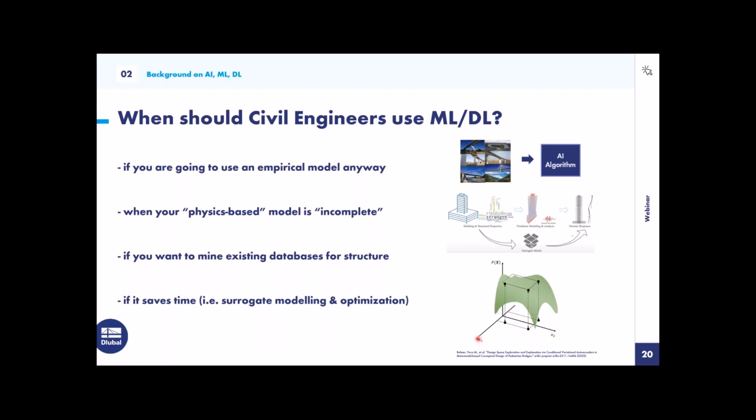Our design problem can be a length, a section profile, or a material. And what we usually do not know is this greenish surface. The idea is that all of your structural models, for example a bridge or a house or a truss, live on this parametric manifold. So if I change the cross sections of that cantilever we looked at, I would go along these lines here, right, on that surface.